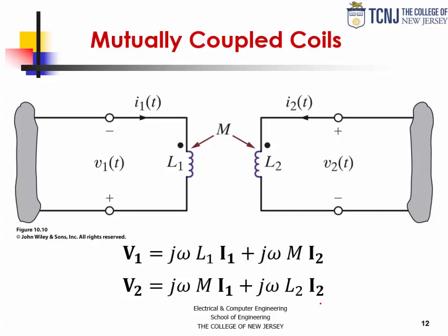Note that the current vectors are going to take care of the minus signs for the mutual inductance terms depending on the polarity on the secondary with respect to the primary. Since the currents are vectors, they will have a direction and an angle as well that will take care of the difference in polarities.